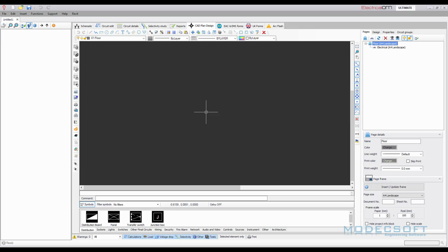As you can see from the left toolbar, we can find tools where we can manage external references. We can export into DWG format. We can create printouts. We can view our drawings in 3D modes and so on. From the top toolbar, we can find familiar tools and commands where we can edit our drawings. From the right toolbar, we can enable and disable snap points and so on.